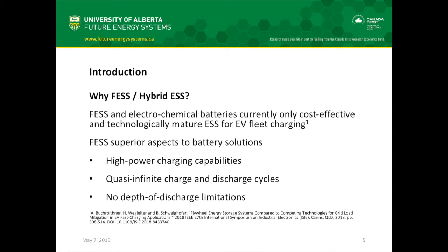As I've just mentioned, FES has high power charging capabilities. Another drawback is that you have to replace the batteries over time, but in this case, there are almost quasi-infinite charge and discharge cycles for the flywheel energy storage system. Apart from that, batteries have depth of discharge limitations, but there are no depth of discharge limitations in the case of FESs.